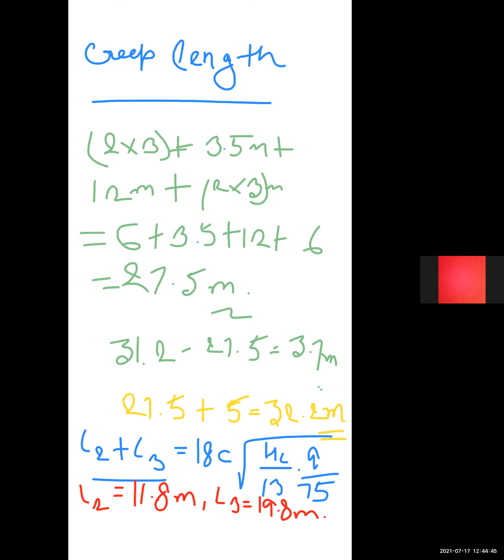So hence provide a thickness of 1 meter downstream loose talus of 20 meter in length. So for downstream length it is 20 meter. So 20 meter can be partly provided as block over inverted filter and partly as launching apron. So the length of upstream, that is L4, may be kept as equal to half the length of downstream.